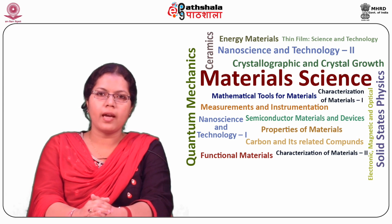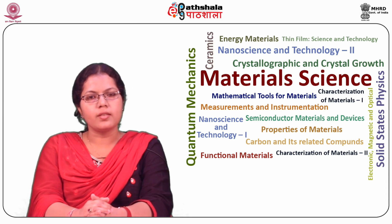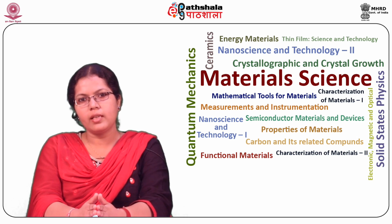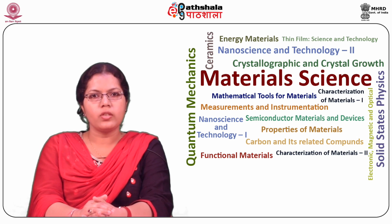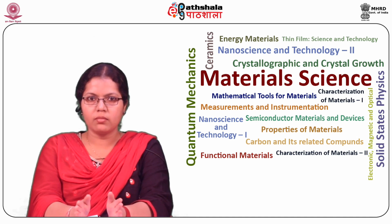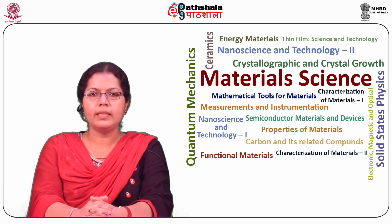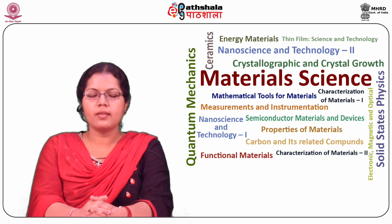The design should be such that accurate measurement of physical dimensions is possible. The materials used should be such that the value of inductance remains constant irrespective of the environmental and circuit conditions. This requires that the materials used should be such that their dimensions do not change with time, temperature, and humidity. The inductance should be independent of the value of the passing current. This requires that no ferromagnetic materials should be used.